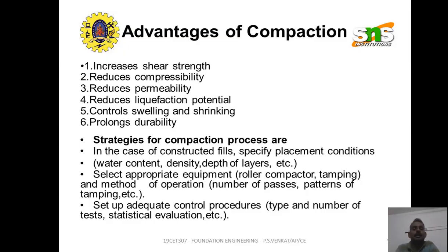It reduces permeability of the soil so that there won't be seepage of water inside the soil mass, and thereby the percolation of water can greatly be reduced. It also reduces the liquefaction potential of the soil. So what is liquefaction? Liquefaction is a process of loss in shear strength of the soil due to vibrations or shocks which the soil mass is subjected to in case of natural calamity such as earthquake.